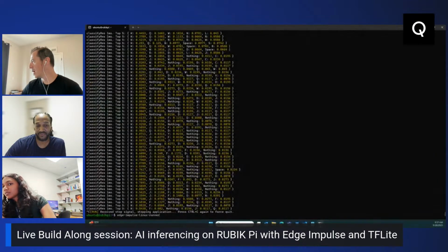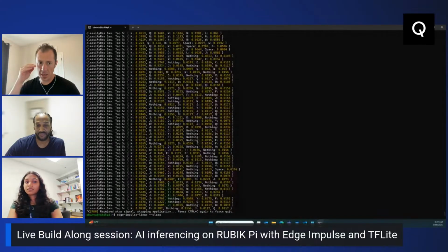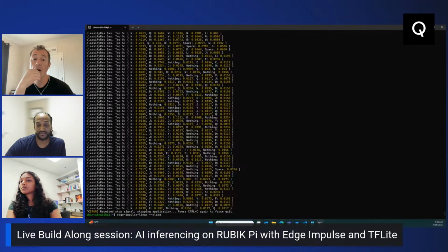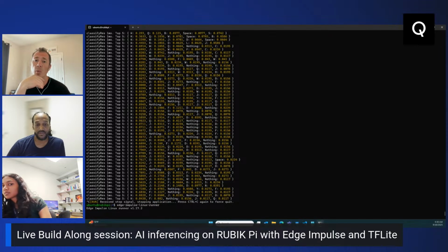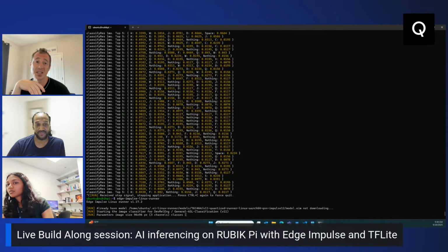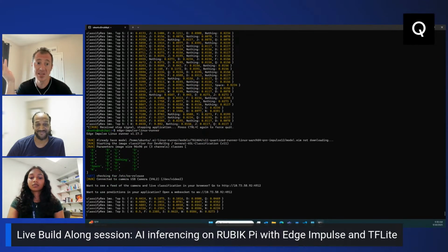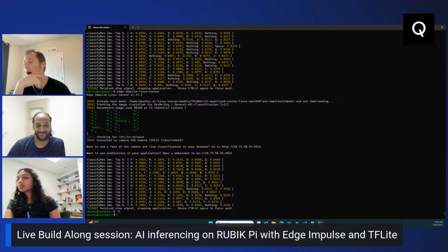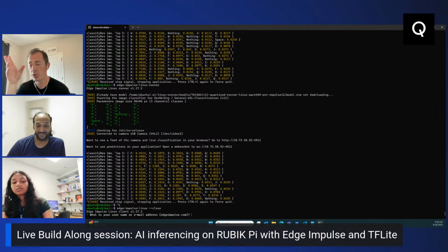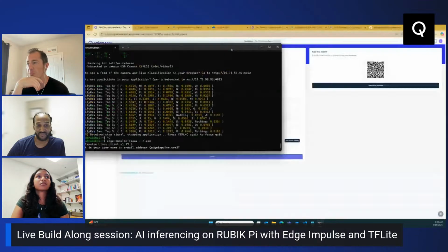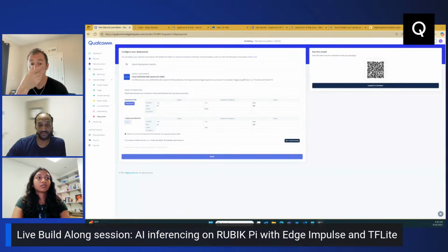Is that true? Yeah, the Hexagon needs int8. So if you go to float32, you're going to run on the CPU, which is possibly just fine. It depends on the camera resolution, model size, parameters, so there are a lot of dependencies there, but in this particular case, classification will probably run just fine on CPU as well.